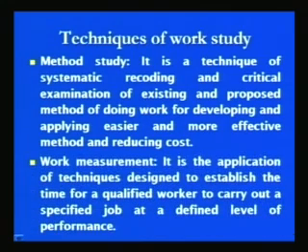On the other hand, work measurement is defined as a group of techniques which are designed basically to establish the time for a qualified worker to carry out a specified job at a defined level of performance. In fact, the work measurement helps to find out the time required for carrying out the job by a qualified worker at a specified level of performance. At the same time, when work measurement is carried out, it reveals the ineffective time if it is there. So, the presence of ineffective time helps to identify the areas where method study can be carried out.